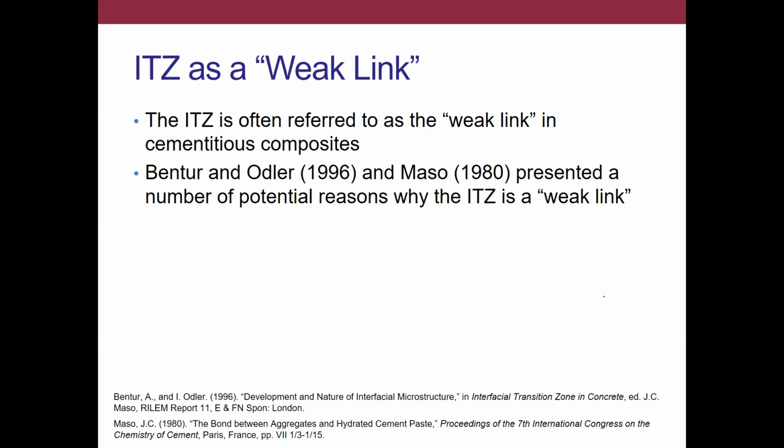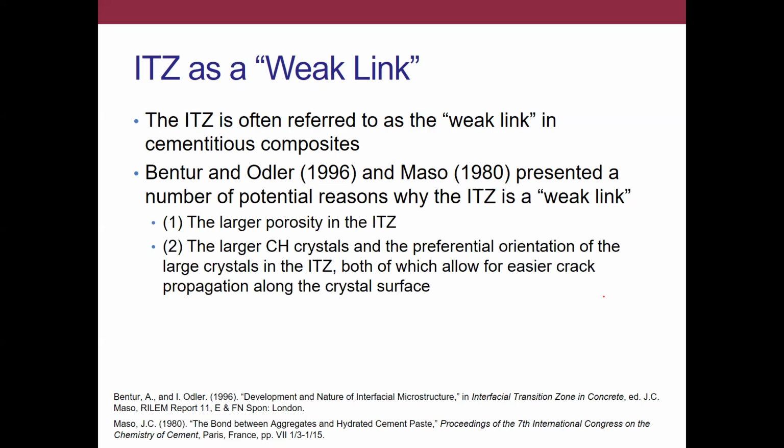The literature pretty much presents that there are three primary reasons why this is. Number one, the larger porosity in the ITZ. More pores, of course, already means that we'll have a lower modulus composite. It has been proposed that those large calcium hydroxide crystals that form allow for easier crack propagation.